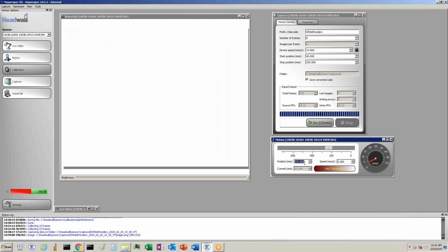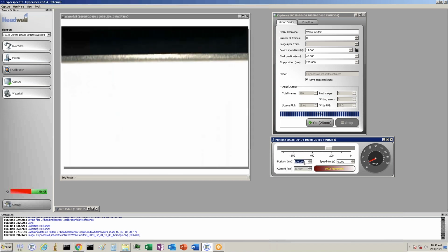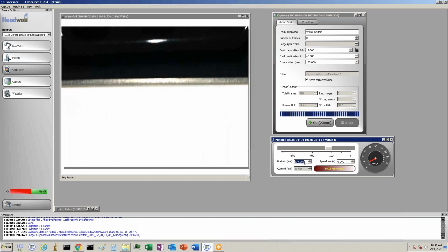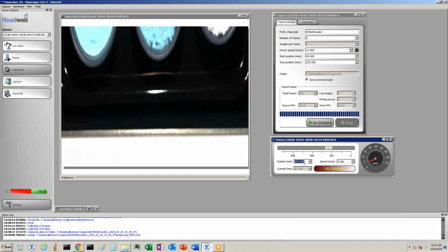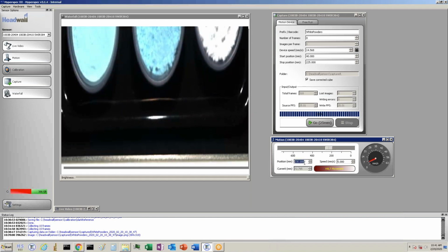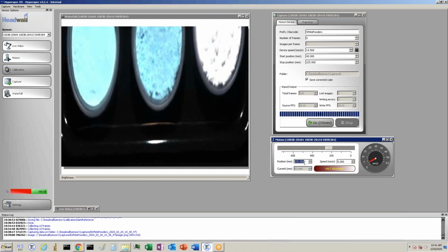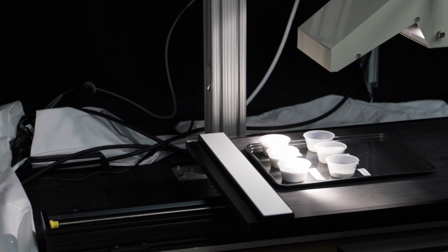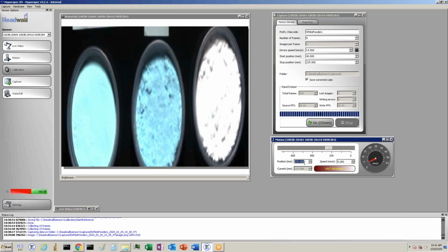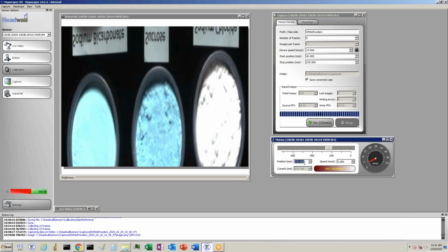So this, of course, takes longer to demonstrate because we are moving the scanner slower. Well, you can see instead of having nice round cups, we have elongated oval-shaped cups. Because again, we are scanning too slow, which elongates the pixels in the direction of travel.